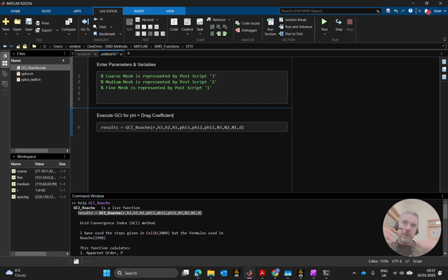What happened then was when we changed, I think the pitch on that, at that one grid refinement, it wasn't able. New physics were brought in, which introduced an instability. So I think it was more of a physical breakdown, more so than a discretization breakdown, which we could calculate. We could calculate better at that angle of attack, possibly using a different turbulence model, or maybe using a different discretization scheme, or a different resolution of our mesh. All right, so it doesn't mean it's always going to fail at an angle of attack of 5 or 6.